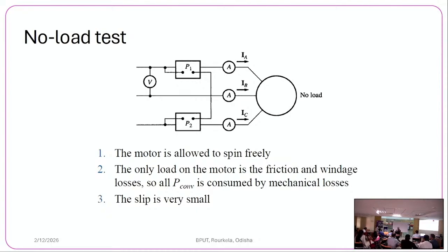Current flows only in the outer surface, not in the inner core. At very high frequency it will flow only at the surface, and the inner part will be useless. Though the actual conductor is solid, current is not flowing in the inner core, so it is of no use.